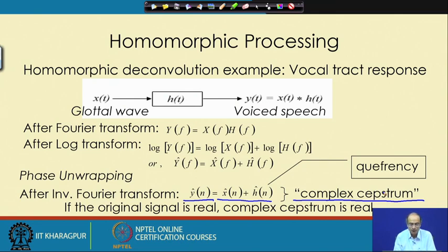Why are we telling it in that way? Because this complex Cepstrum has gone through some transforms and is not the same as the original time domain. The Fourier transform and inverse Fourier transform were taken, and in between a log was also taken, which makes it different. This complex Cepstrum has some good properties.